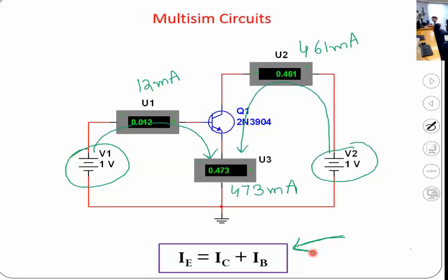So once the base gets to 0.7, you get 0.7 volts. Again, that 0.7 is only going to be on the base in relation to the emitter. On the collector side, you may get something different. See, there are two loops here, correct? One loop is on the base side.